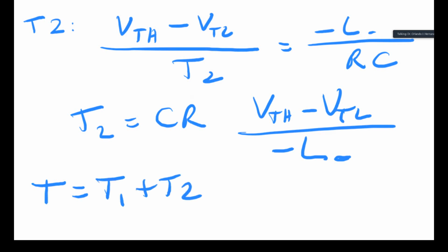So here you have a circuit that gives you a square wave, it gives you a triangular wave, and then what you can do is add another op-amp based circuit, and you can filter the fundamental out of, say, the triangular wave. You can filter the fundamental and then you get a sinusoid. So now with another pretty simple filter and 3 op-amps, you have a function generator for a square wave, triangular wave, and sine wave.